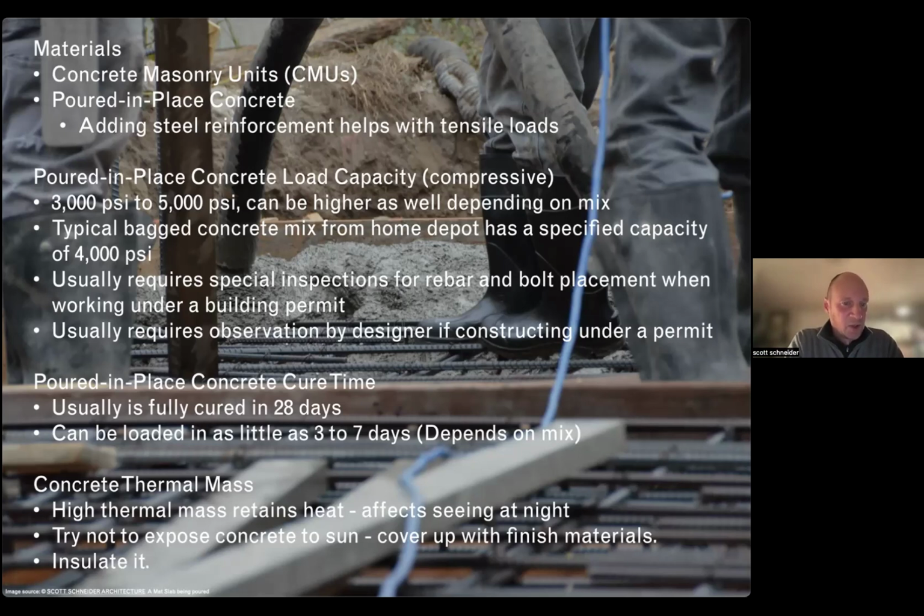A lot of times concrete is used as a thermal mass for passive heating in houses or other types of buildings. One way to deal with that, though it's not going to totally fix it, is to cover it up. Don't expose it to the sun, put insulation around it. Ideally, you don't build your whole wall out of concrete. You limit it to the ground and try to cover it up.